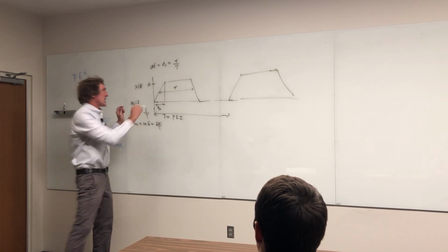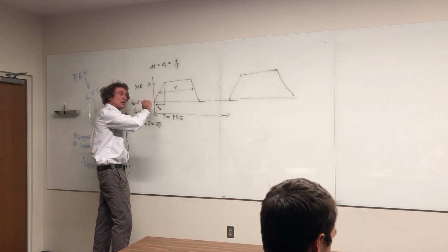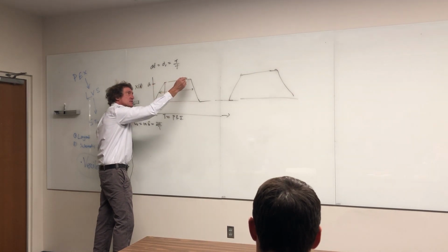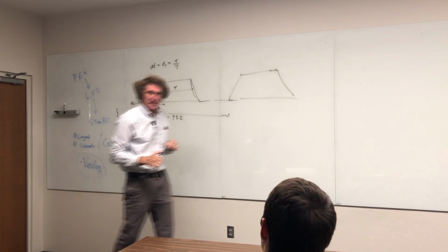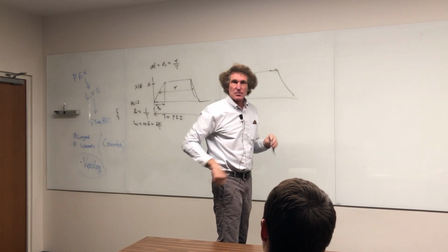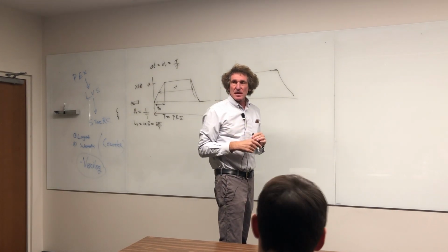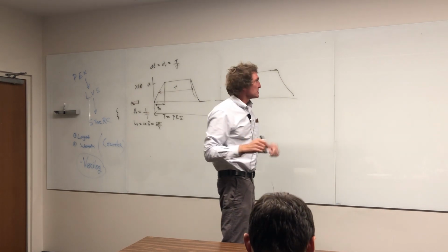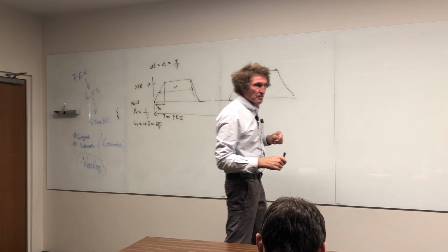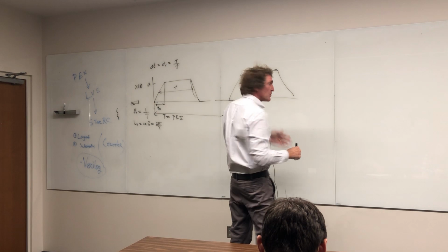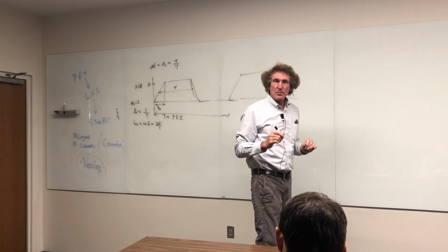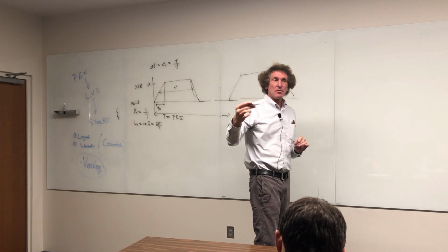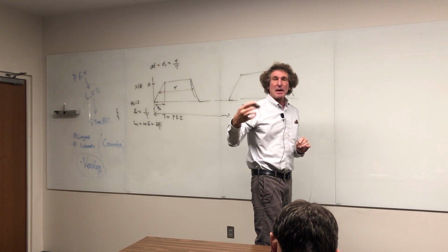These are actually exponentials, but this is the very early part of the exponential, and this is the very early part. They're not exaggerated like that. This is basically an exponential decay, but just the first part of it, so it's much less than several time constants. If we have that waveform, we know we can express it as a Fourier series, a Fourier cosine series. But the real thing we want to do is take a look in the frequency domain at what the signal spectrum looks like.